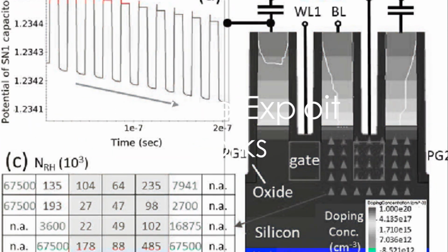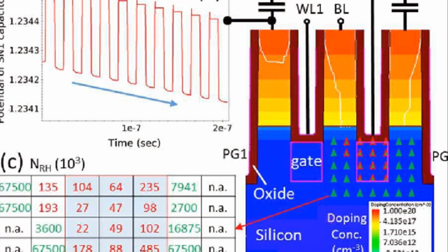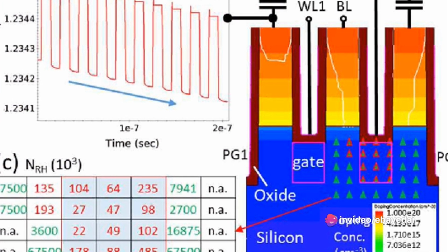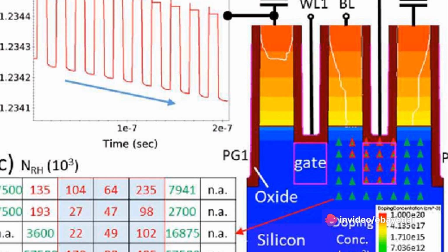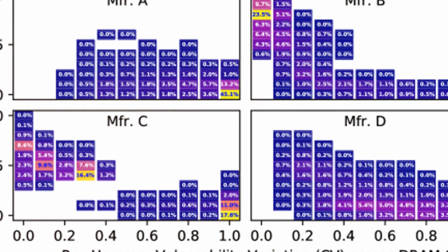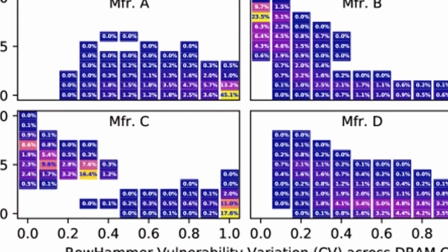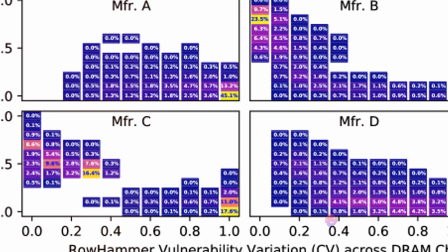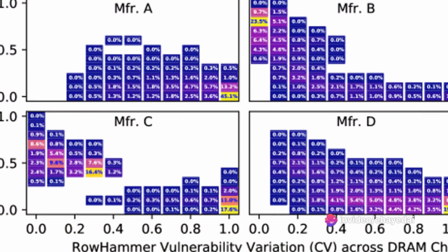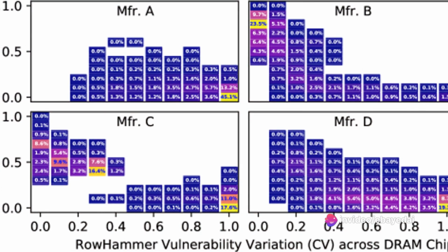The opportunity for the Rowhammer effect to occur in DDR3 memory is primarily attributed to DDR3's high density of memory cells and the results of associated interactions between the cells, while rapid DRAM row activations have been determined as the primary cause. Frequent row activations cause voltage fluctuations on the associated row selection lines, which have been observed to induce higher than natural discharge rates in capacitors belonging to nearby, adjacent in most cases, memory rows, which are called victim rows. If the affected memory cells are not refreshed before they lose too much charge, disturbance errors occur.